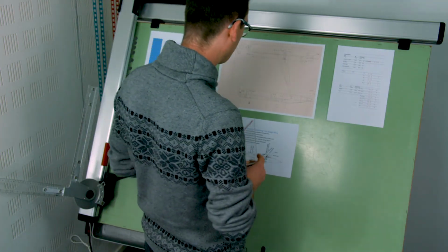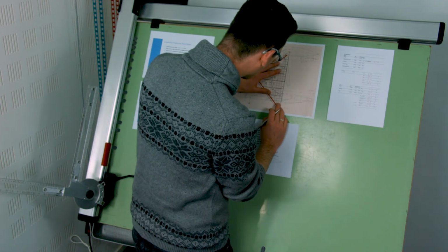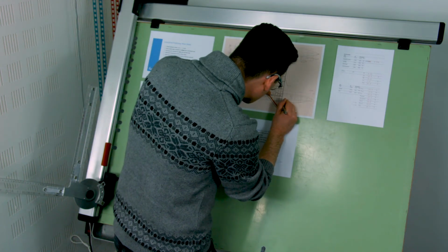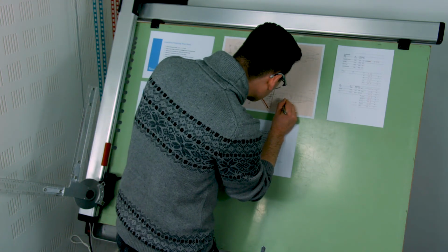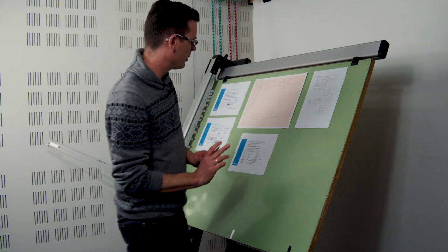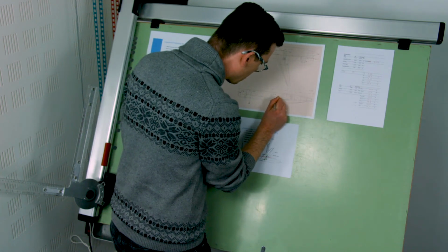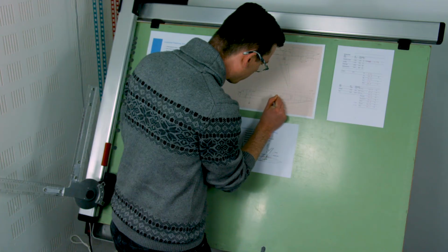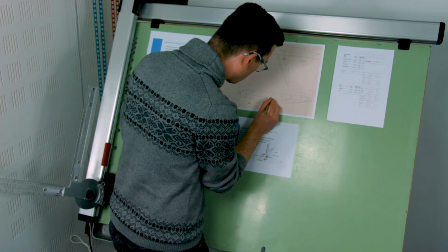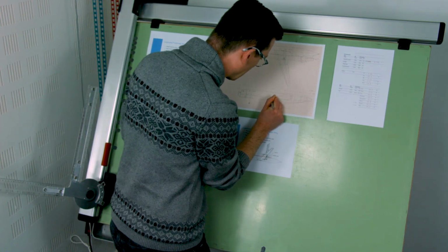If I would do it perfectly right, I should also correct this in the side view. So I'm also marking this spot here, because now my root airfoil is going to grow as well. Assuming the same thickness to chord ratio, my root airfoil is going to look a little bit different. It's going to be a little bit thicker in absolute sense. And that's, from a structural point of view, absolutely not bad at all.